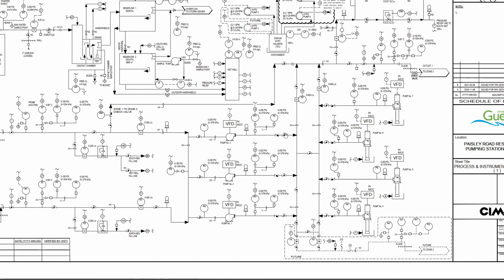We've got 2 hand valves for isolation. If we ever need to do maintenance on the pump, we close this valve, we close that valve. We can drain the water from here, open up one of these, it spills onto the floor, we can do maintenance on the pump. The discharge of the pump runs into this header. In the future, we would discharge into another line.